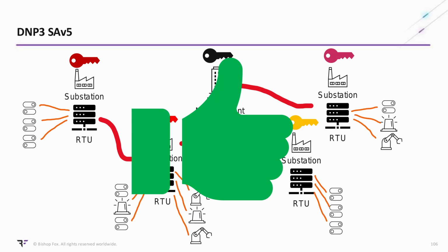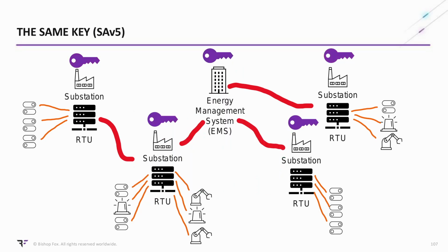By default, or I should say by the specification of DNP3 SAv6, all of these keys are in fact the same key. It's just a symmetric key. They're all the same key. So you tried. So the substations are still perfectly capable of operating all the other substations.